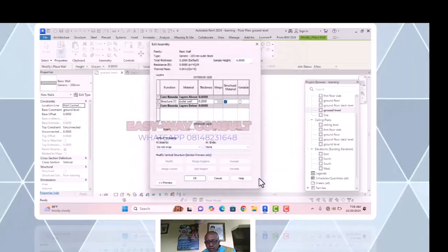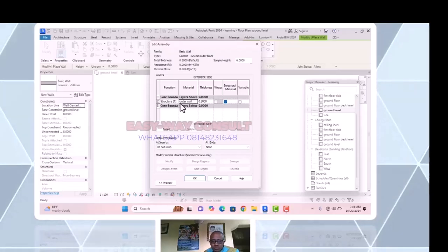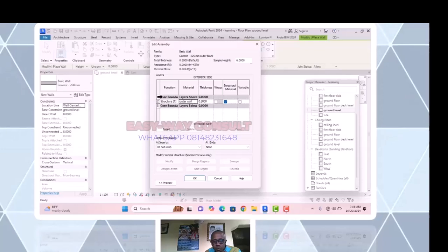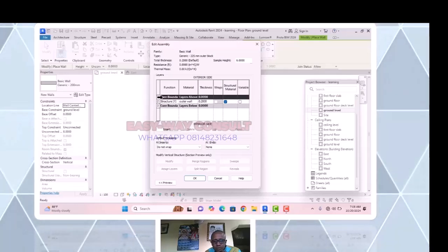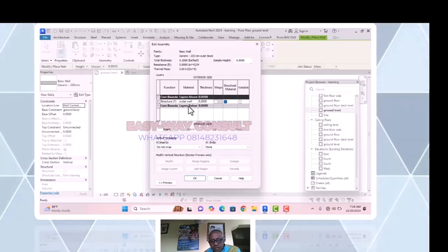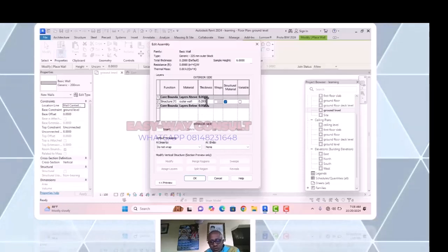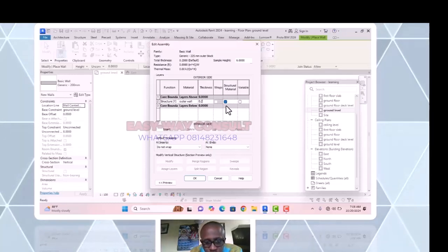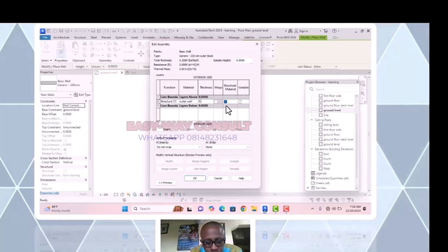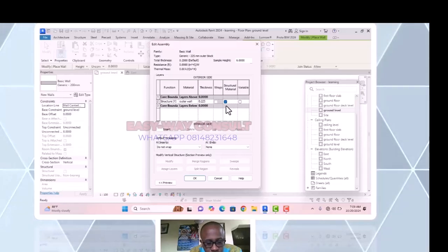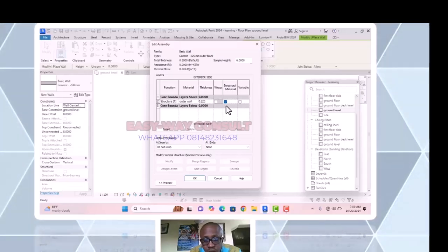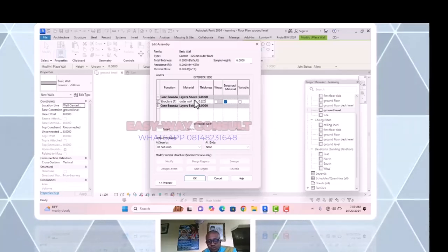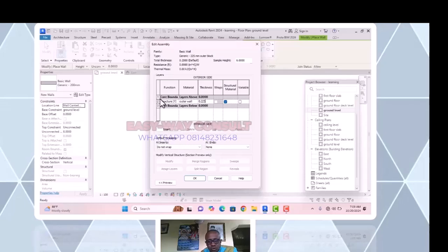Then okay. Then if you want to paint it, you can come here. This is where you will come and paint. You click here. Here now you can select other material. No, first of all you go here. You change it because it is 225 we are using for outer. This is where you can change the size. 225 is what we are using for the outer wall. You change it here. 225. That's for the block.